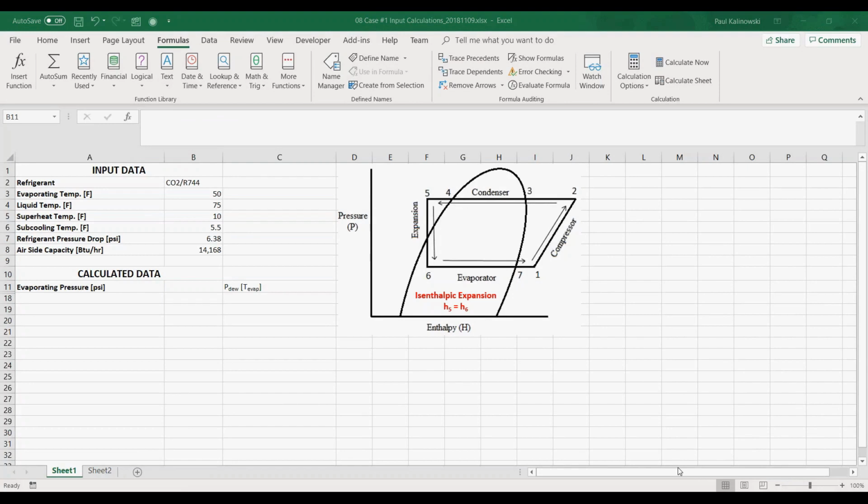If you don't know all input parameters for your CoilDesigner model, we recommend using third-party software such as EES or RefProp to calculate them. At Optimized Thermal Systems, we use software called XProps. XProps uses the RefProp database for the refrigerant properties. XProps can be used with different software such as C#, Visual Basic, and Microsoft Excel. I'm going to show you how we use XProps in Microsoft Excel.